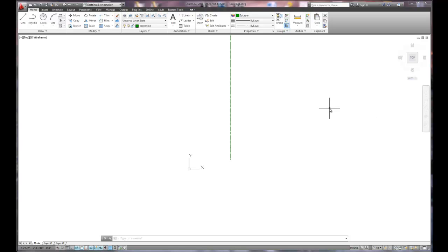I'm going to double click the mouse, and you can see that my screen image has changed. If I roll my mouse back one click, you can see that I now have the full line on my screen. You'll also notice that the scaling of the line type, I can no longer see the dashes very well. And so this poses another issue. There is a command called line type scale.